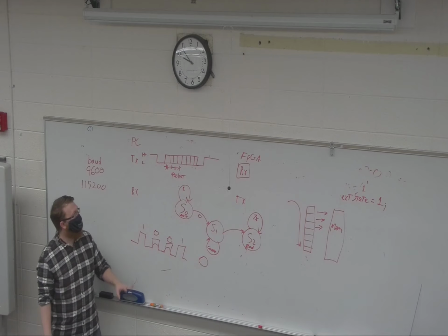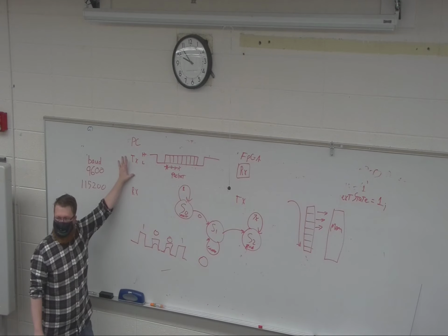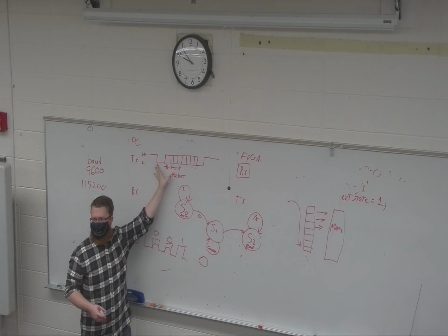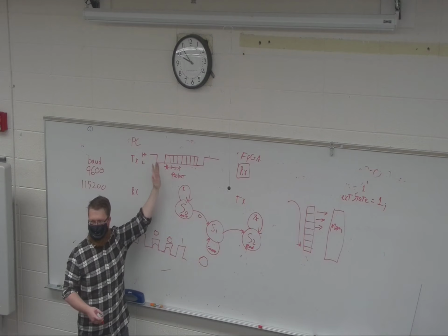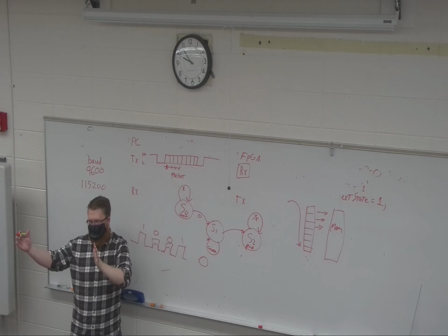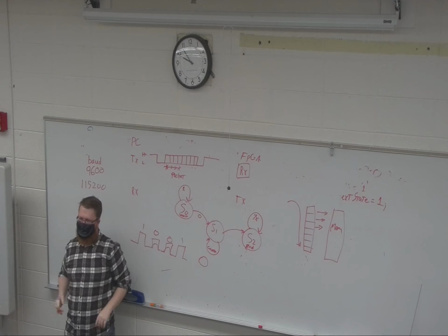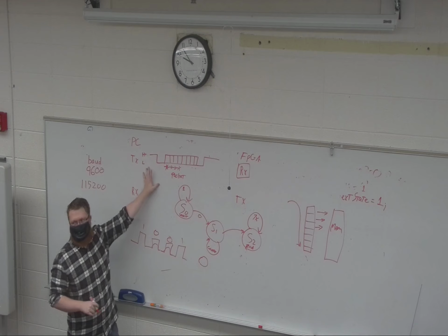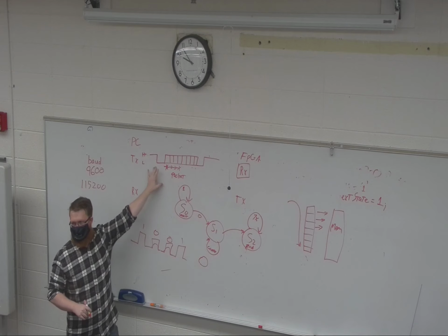And so, having done designs like this, when I hand it off to someone, I have a packet definition. Because a lot of times you'll actually have a much larger packet that will have like a command in the beginning. So it'll have a start bit, a command, data, and then some sort of verification, which is more complex than just a single bit parity. So you can build up fairly complicated packets, but this is the simplest one.